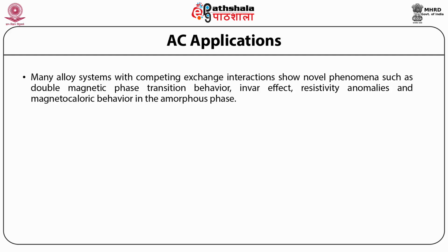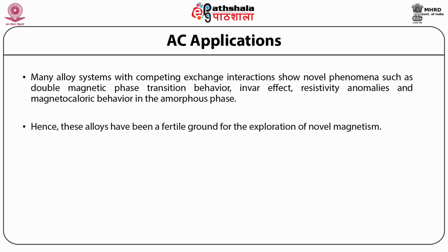Furthermore, these alloys in nanocrystalline state exhibit outstanding soft magnetic properties such as ultra-low coercivity, high saturation magnetization, and high permeability. Hence, these alloys have been a fertile ground for the exploration of novel magnetism. It is well known that the general composition of such alloys is LTM-ETM-M, where LTM is generally body-centered cubic BCC Fe in the range 50 to 93 atomic percent. ETM typically consists of zirconium, niobium, hafnium, etc.